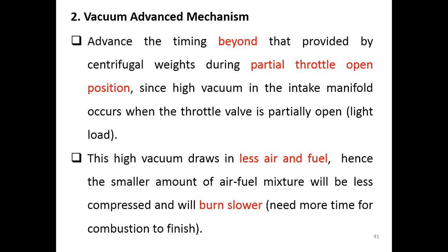Remember, the engine is under partial loading, so we have less air and fuel mixture flowing in. A small amount of the air-fuel mixture will be compressed, and the compression is less, which means when it burns, it will burn slowly.